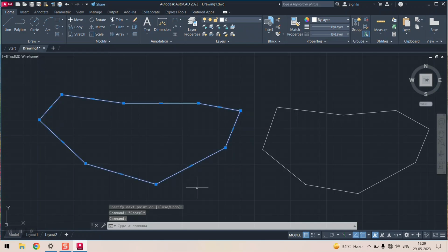So what is the difference between the line and the polyline command? Whenever you click on a drawing made with the polyline option, the moment you select it, it will select the entire model. But the drawing made with only the line command will allow you to select only a section of it. It means a line is basically a single line.